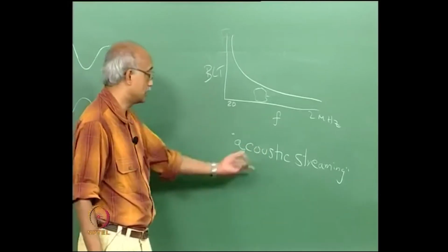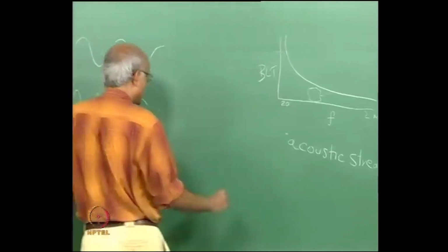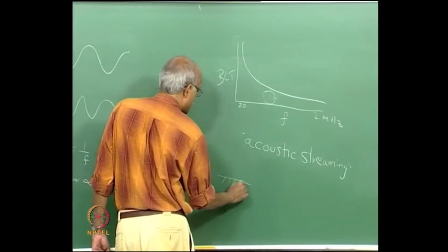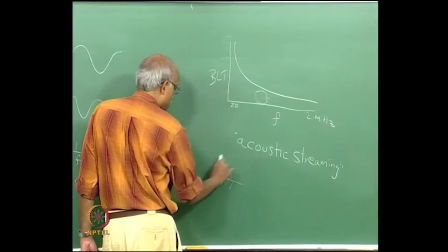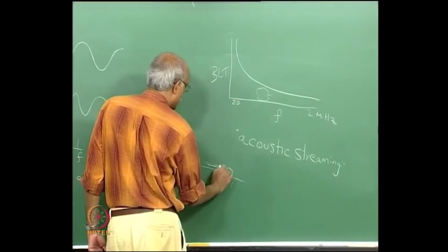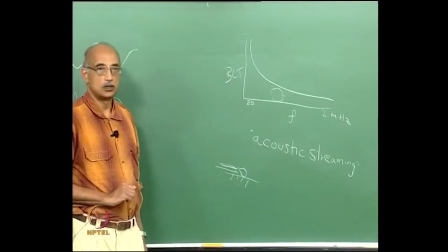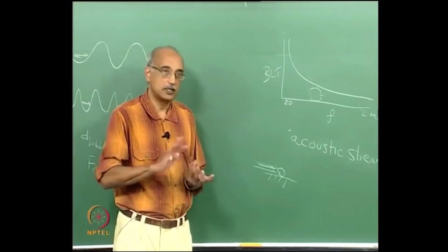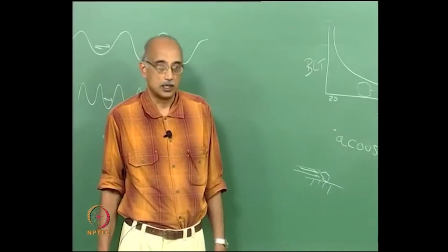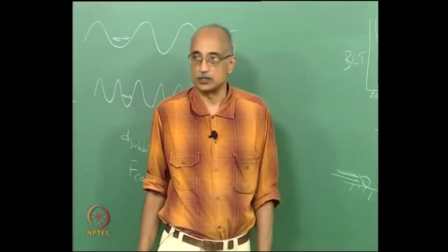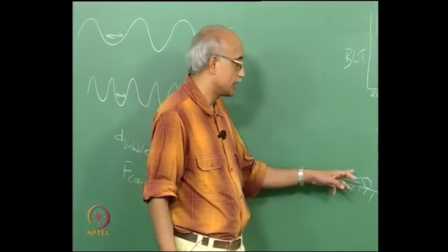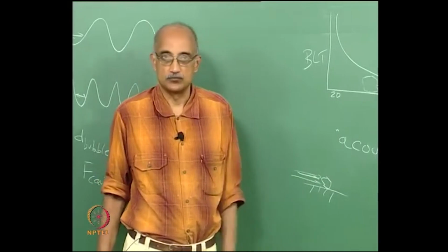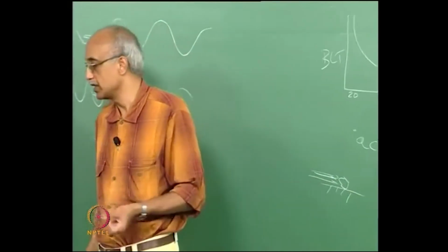If you have particles sitting on a surface, acoustic streaming results in extremely high velocity flow of liquid over the surface. Compared to a general spray cleaner, you can achieve velocities in a megasonic cleaner that are 100 times higher. 1000 meters per second flows are possible in a megasonic tank. But it is basically a shear based cleaning mechanism, which means it has its own limitations.